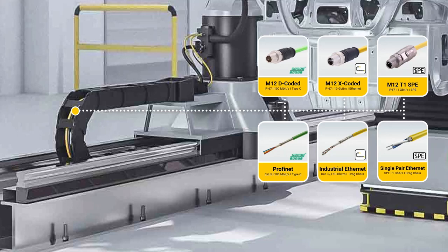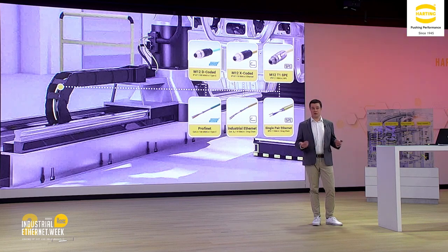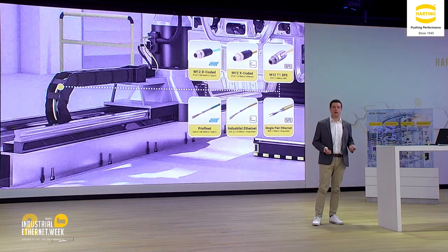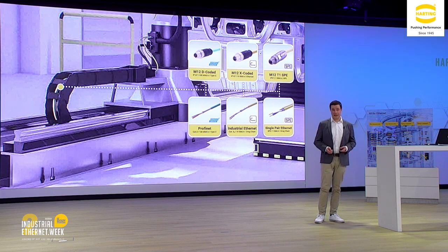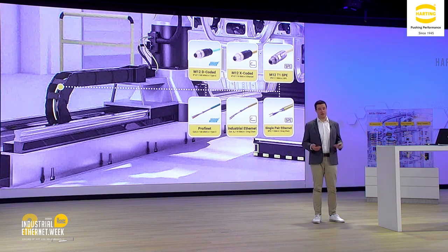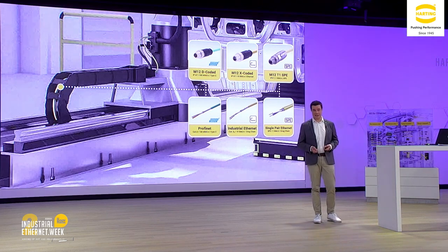Here we have a guided force on the cables, or bending, and the cable assemblies are also available ready-made with standard connectors for this kind of application, like the M12 D-coded for 4-pole Ethernet transmission, or the X-coded cable assemblies for Cat6a transmission performance, for example, for camera signals or something similar.